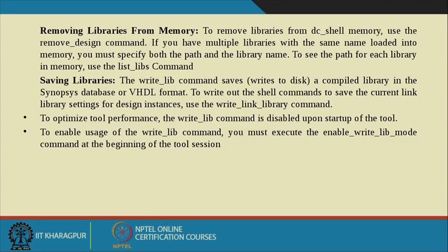Okay. So before starting with the next design, you have to do this remove_design, otherwise all this information will be saved in the Synopsys memory. Next, how can I save a library? The write_lib command basically saves your library to disk. Okay. You can save it in .db format, .v format, or .vhdl format, in any format.